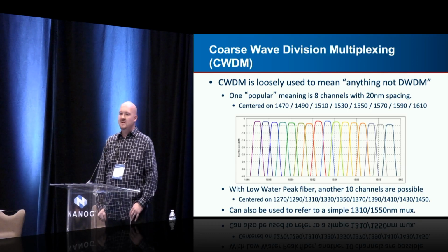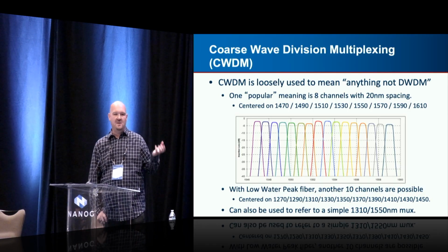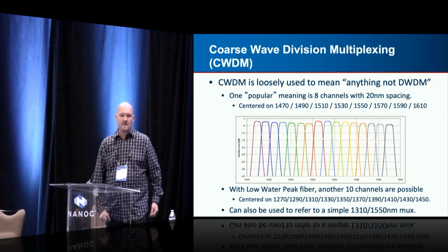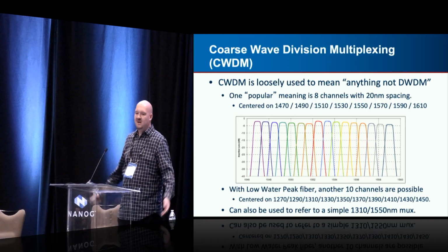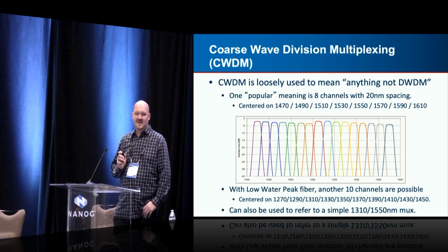It can also be used to refer to something like a 1310, 1550 mux, where you just take these two really simple common frequencies, put them together, and call that CWDM. Or as friends of mine have called it, GWDM, ghetto WDM.